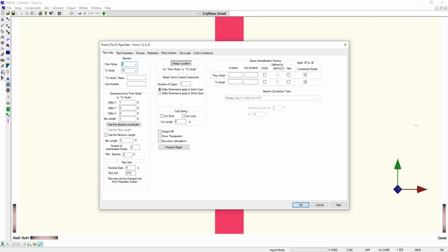Okay, structural is AISC. It's attached in the same model. There is no reason to go to a different viewing screen or anything else. You attach it using the release components because you have to define, is that pipe shoe stopping it in the axial? Is it stopping it in the guide? So you have to define the structural attachment using the release component. And then, of course, we have a PRV as well.